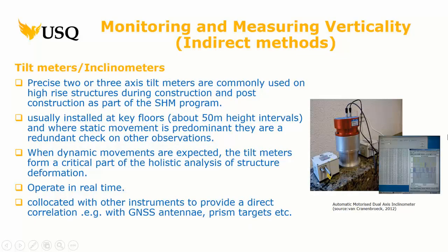Okay, so that's a tilt meter. This is a modern style one, right? Has data inputs. Really, it's just a box, right? And you can see the output here is actually movement, a bit like a seismograph, right? So the change in tilt is measured. They're not super cheap, the things used in buildings, but they're cheaper than surveying. Right? So you put them in, you probably leave them.